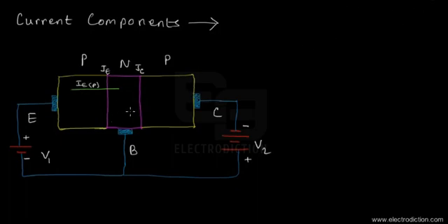the base would also have the majority carriers of electrons inside itself. And now the electrons, under this applied potential over here, would also start flowing across the junction, but just in the reverse way. So I'm just going to show that with a different color over here. So the electrons from the base would just flow into that of the emitter. And that way we would just call it the emitter current, that's IE, the same symbol. But this is due to the electrons that are flowing from the base into the emitter section of the BJT itself.